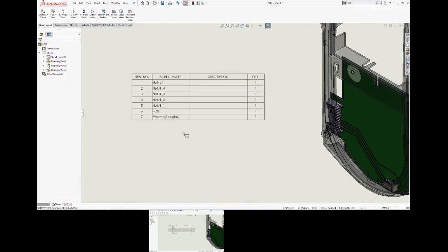Because now we're not talking about STEP, we're not talking about dumb data that represents the PCB. Parameters will come, because now I have a true representation of those components and the board in SolidWorks Mechanical. I can pull parameters as well. That's an option you can enable. So I can also have a BOM available as a choice. In your environment, I can include my components. I can include the PCBA as just a line item, and this is your SolidWorks environment. You can customize your BOM as you want.